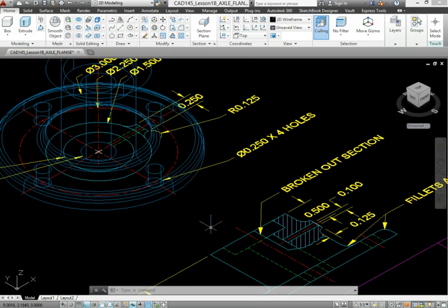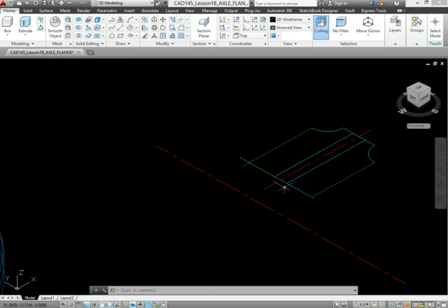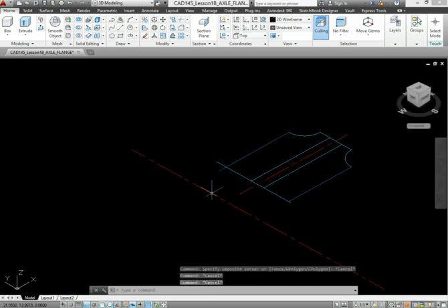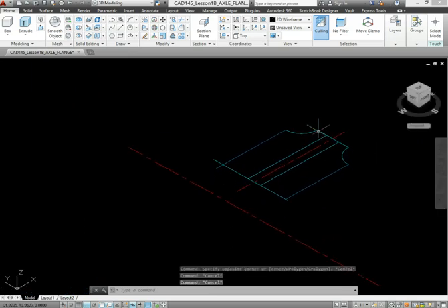The next step is to draw the grease fitting that's going to be attached to our axle flange. You need to copy this area here, including this center line, and a lot of the features in here. I've already done that. I'll show you what that looks like. I've already copied it over. Here's the axis. I kept this section of it, and I drew 2 lines parallel to the other 3 lines here. And now I need to trim these off.